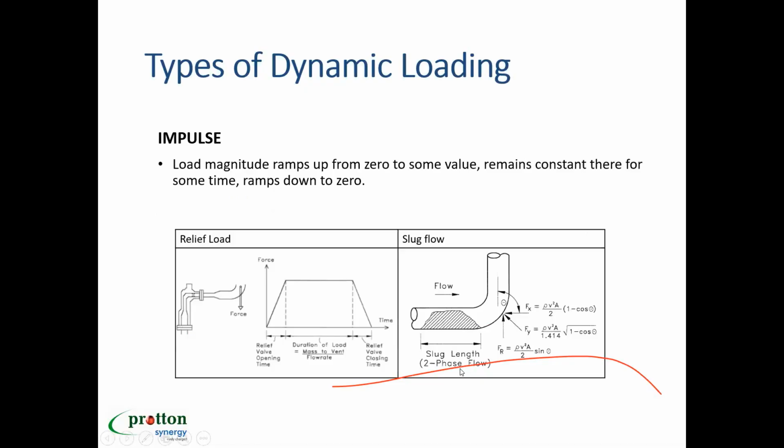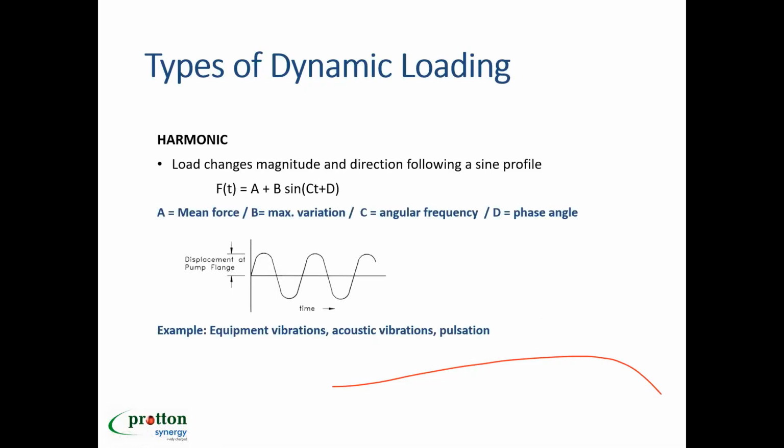Now, the second kind of loading is harmonic loading. Harmonic in the sense, the load which changes with respect to time, but at the same time, we know the pattern of it. For example, the fan is making noise with certain RPM. Compressor is running with certain rotations per minute. Turbine is having certain rotations per minute. So we know that the frequencies which are getting generated, the excitations, are with respect to time, and we know that pattern very well. So when you know a pattern of the excitation, like a pulsation, the compressor vibration, turbine vibrations, those are under this.